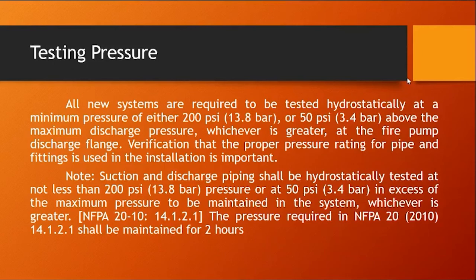Note, suction and discharge piping shall be hydrostatically tested at not less than 200 psi pressure or 50 psi in excess of the maximum pressure to be maintained in the system.